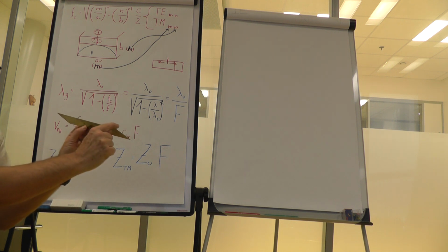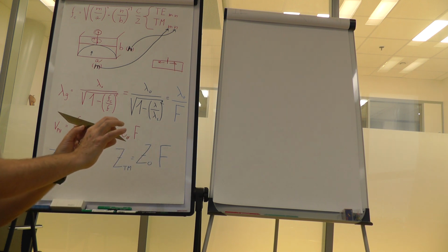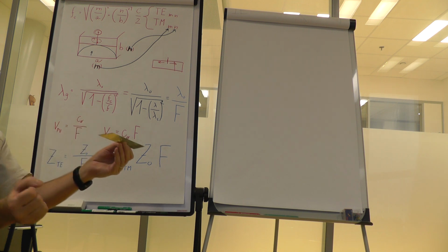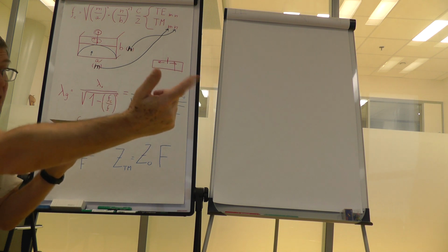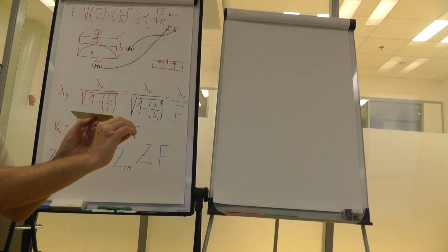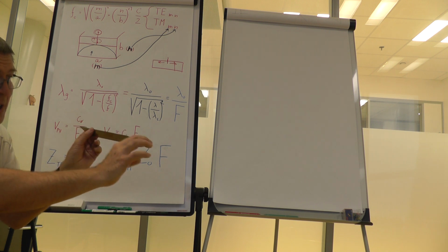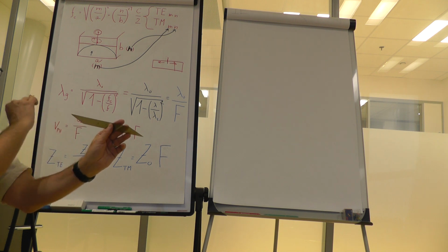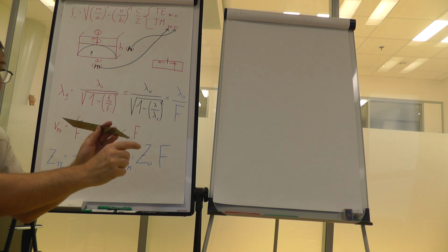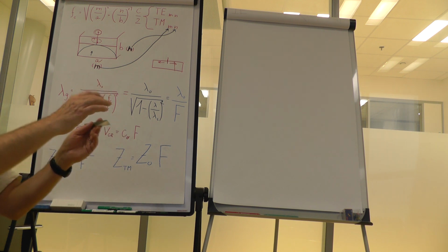Now, why is this not straight at the end? Why have we bothered to make it, let's say, gradually increasing its dimension in the direction of propagation? Well, if we had made something very straight, there would be a reflection of the wave, but now the wave gradually gets used to the metal insert, and the same at the end. So this is made so to decrease reflection.